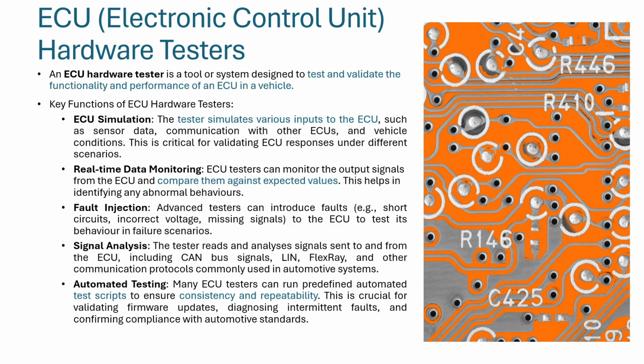Fault injection and diagnosis. Some advanced testing hardware units are able to introduce simulated faults like short circuiting, incorrect voltage, and missing signals, etc., to the ECU unit, and we can verify the behavior of the ECU unit under such a faulty condition, such a failure scenario. This ensures the reliability of the ECU unit.